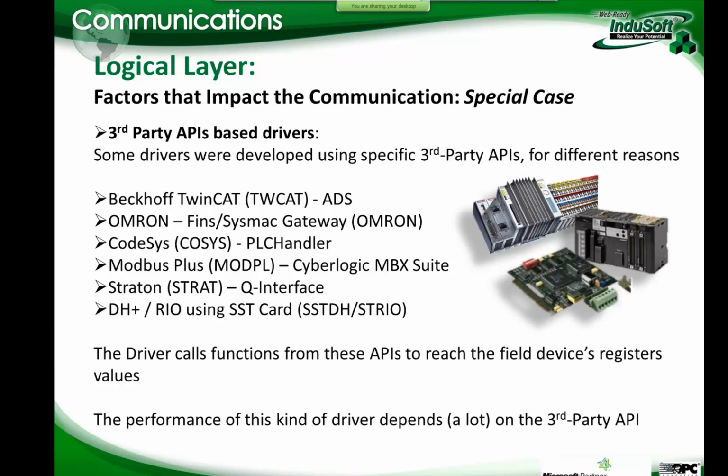We go through CODESYS with PLC Handler. So on those, when you have specific third-party APIs, what we do is we're not going to talk to the PLCs, we're going to talk to the APIs only. How the API gets the data from the PLC into our tags is going to be up to each one of those manufacturers. For instance, Beckhoff, they're talking to the PLC and refreshing their database.